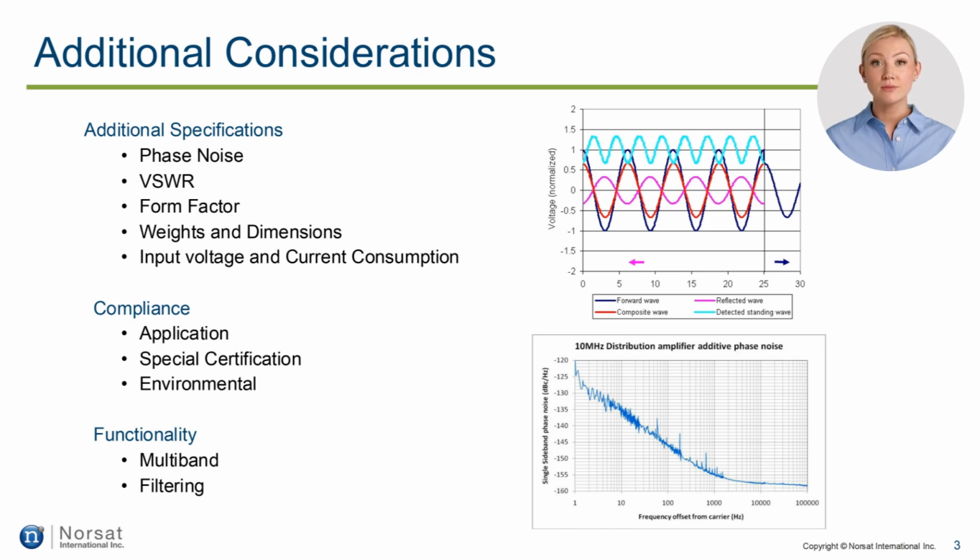One last consideration that would affect the performance of the LNB is external interference. Depending on other RF sources, antennas, electrical installations, or terrestrial communications, you might need to consider additional filtering to improve the performance of the LNB. Some LNB options provide additional filtering within the subband. One of the most discussed topics affecting satellite communications nowadays, especially the C-band, is 5G communication. Alternative LNBs with additional filtering to reduce and mitigate the 5G interference on a satellite antenna are now on the market. That will be covered in the next video.